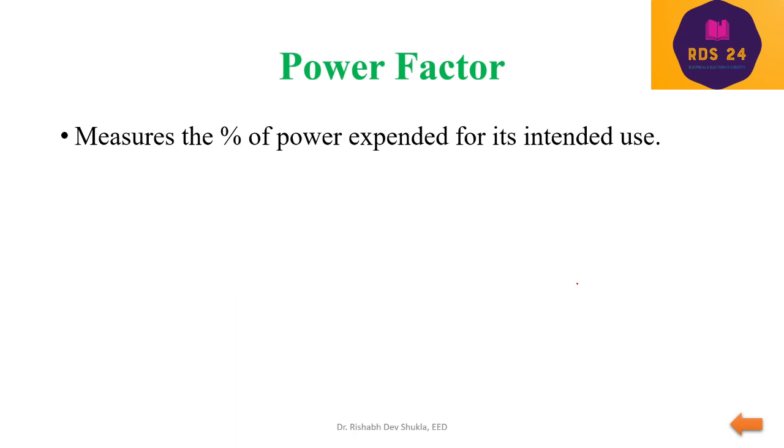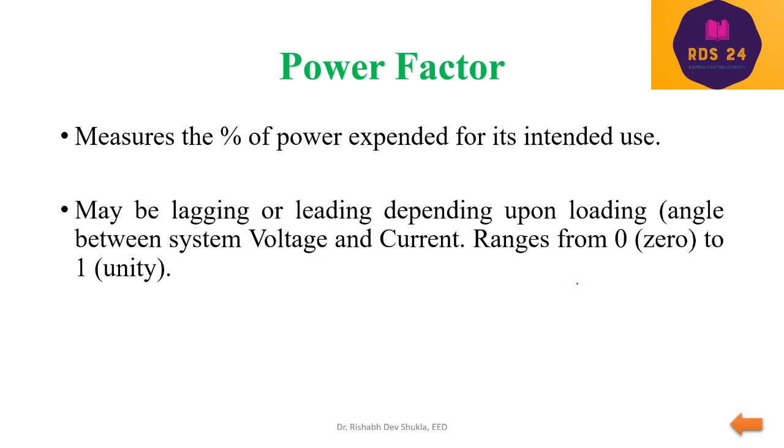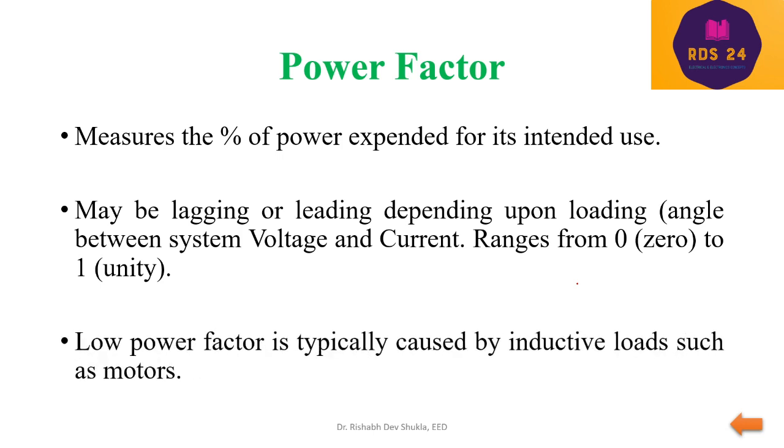So power factor measures the percentage of power expended for its intended use or intended application. It may be lagging or leading depending upon the load. It is the angle between the system voltage and current, and it ranges between 0 and 1. Low power factor is typically caused by inductive loads such as motors. In most industrial applications, we are using the induction motor. So majorly our power factor is lagging.